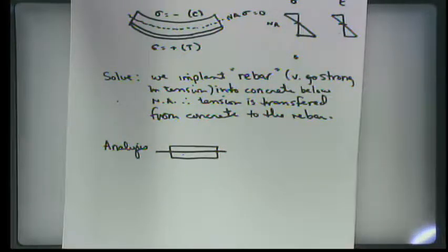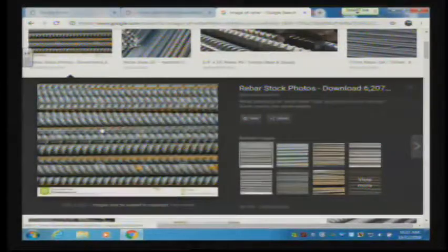Absolutely. And if you ever look at rebar, let's find an image of rebar. Aha, this is beautiful right here. If you look at this picture of rebar, do you see how it has these little grooves and discontinuities in that? That's so that the concrete will form into it. You don't want the concrete to just be around the rebar. You want it to become integral to the concrete itself.